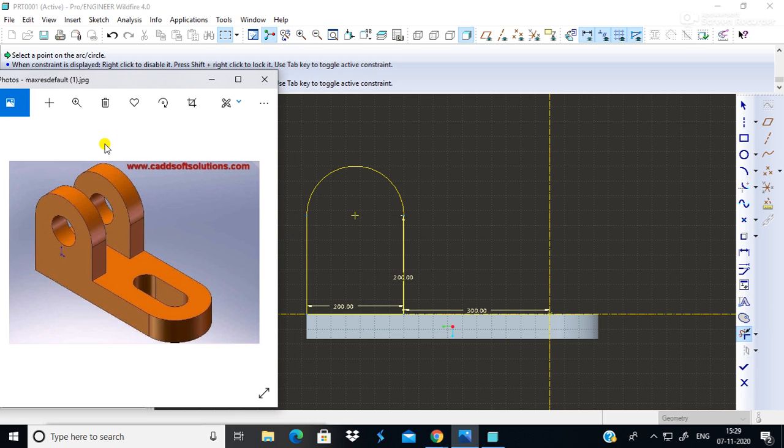Again if you observe it, one more feature is left, that is the center hole. Same way as while drawing the base I drew that slot in it, which reduces my number of steps. Same way here also you can do, while drawing these planes you can also make a hole over here which will help you to reduce the steps, okay.